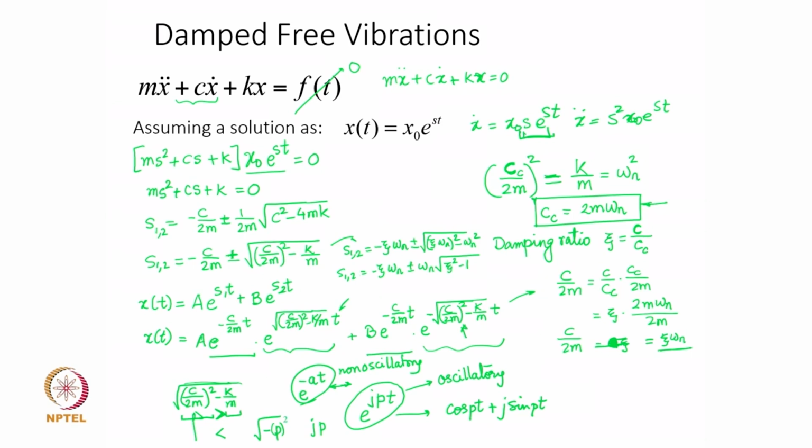Now, in most mechanical systems, this normalized damping is typically less than 1. We shall take the case when zeta is not less than 1 later, but to start with, if zeta is less than 1, then it makes sense to reformulate this expression and write it like this.